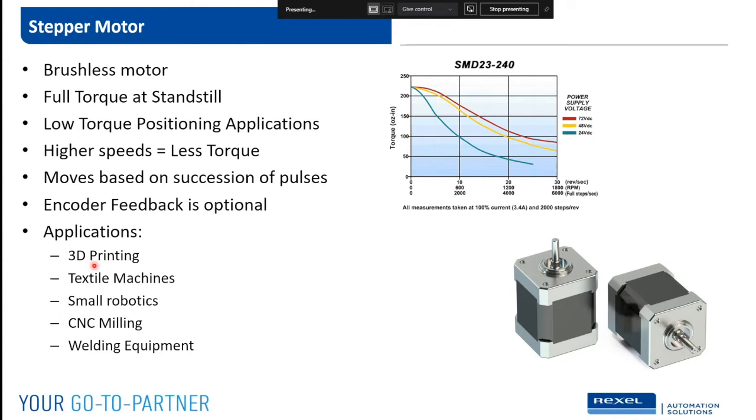One of them is usually on a ball screw, moving the printer jet up and down. It's very precise. It can move at low speeds. And then you also have 2 steppers that are going to drive the XY belt. Usually one's for the table and the other one's for the Y-axis, left, right. And then there's another stepper motor that actually provides the filament. And so they all run at different speeds together in a coordinated fashion.